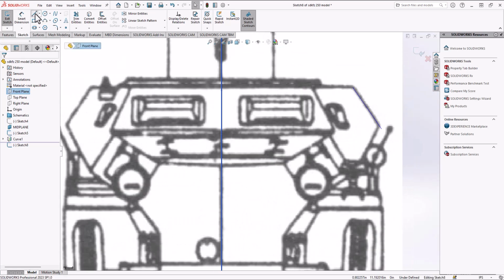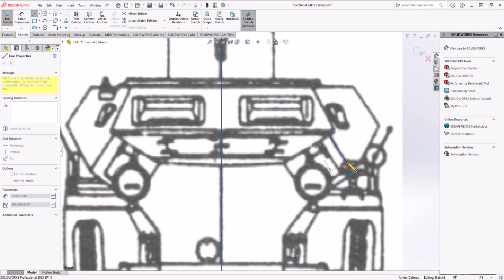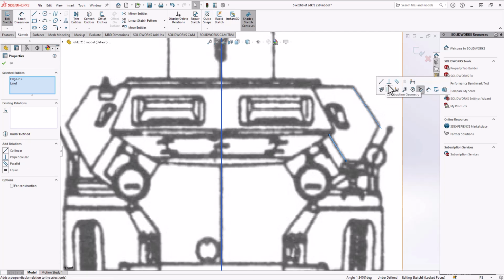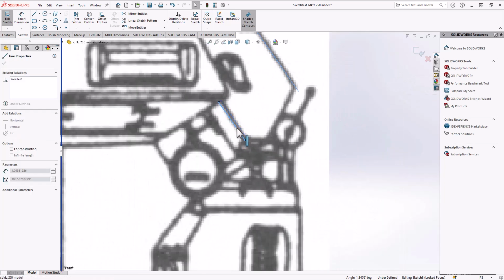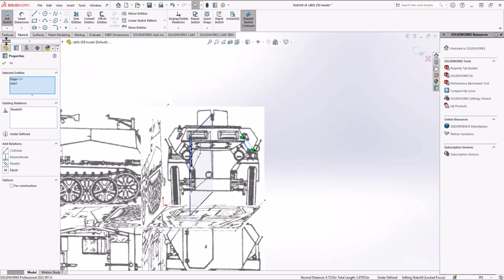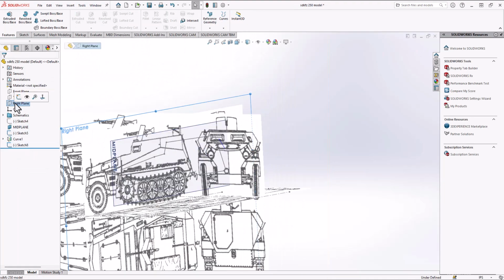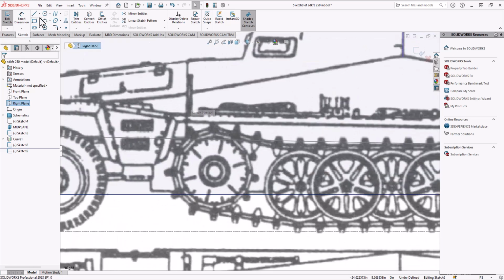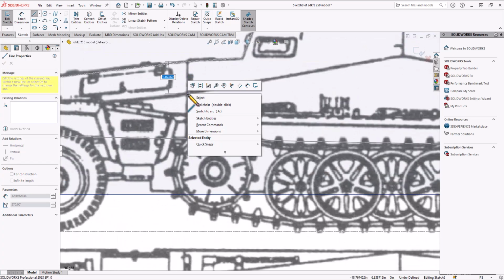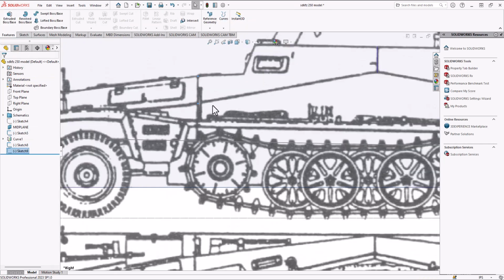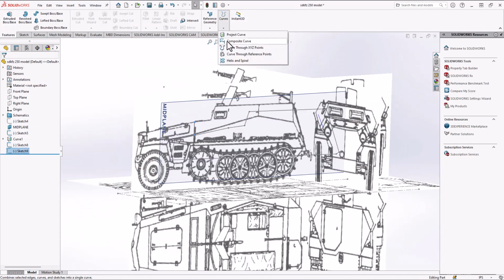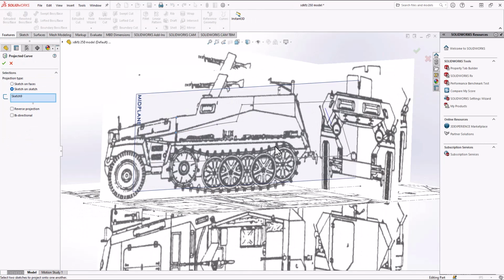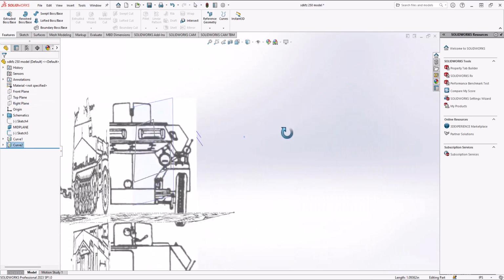So I'm going to create another sketch, and this one should be parallel, since they're both vertical. So I'm just going to make sure they're parallel. I have that, and then I'm going to go to the right plane again and draw that vertical line. Then I'm going to do the same project, and I'm going to draw it between those two. So that gives me these two lines.